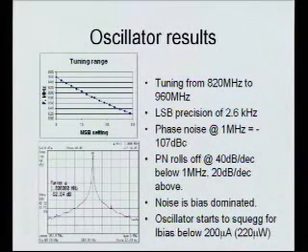And then there's one other effect that we may or may not get into called squegging, a way that sometimes oscillators fail. Usually simple oscillators, when you're not really pushing on power, either work or they don't. If you give it too little power, they just turn off and don't oscillate. You get above some critical bias current or bias power and they turn on.